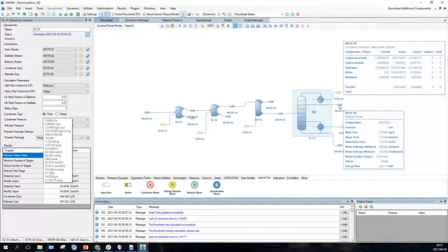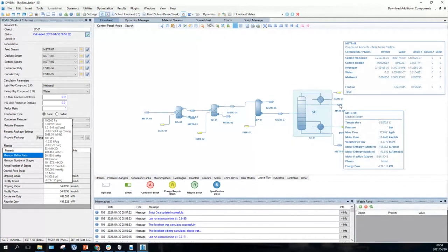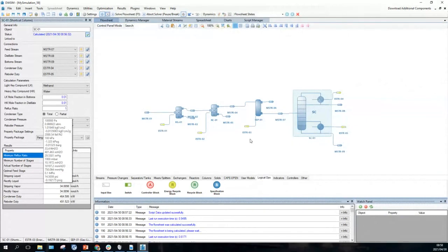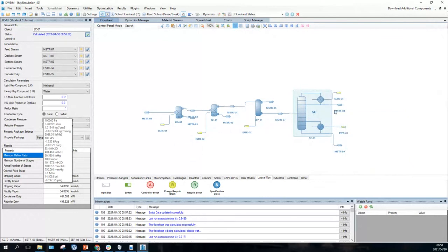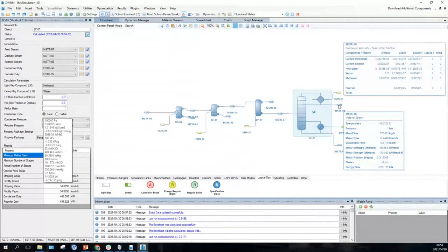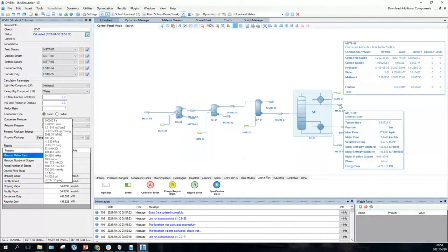And what we want to do is to make that, it's not pretty much pure methanol, it's 90%. But lots of carbon monoxide in there, carbon dioxide in there. Even at 1 bar pressure, carbon dioxide apparently is soluble in the methanol. So anyway, we want to increase the flow rate of this, which is mainly methanol, and we want to see what conditions of the Gibbs reactor will give us a higher flow rate of this.